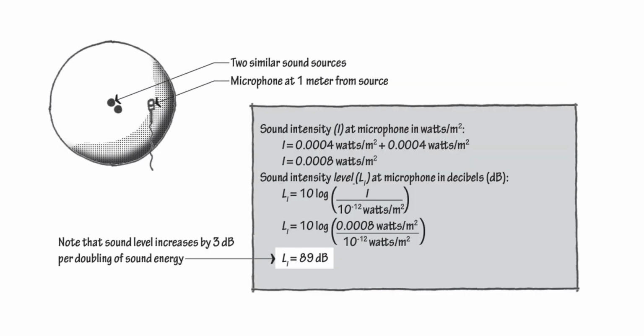When you go for building rating, for example, if a particular room has to be rated at 40 decibels, it means that whatever sound is coming from outside should not be above or equal to 40 decibels. It should be below that. And if it is 41, it means that it is increasing logarithmically, not linearly. We have to keep that in mind.